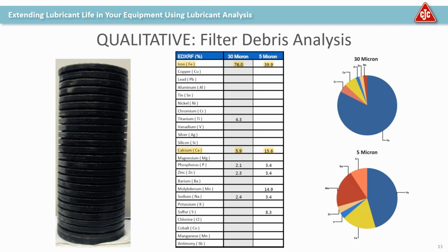And subsequently, this oil has remained in service for many years since this initial cleaning up. The owner was looking at replacing all of the oil, replacing the gearbox even, but instead, just by using routine oil analysis and good filtration, they were able to keep that oil in service, which really is a huge benefit, because for the average wind turbine, the cost savings of just one oil exchange, a conservative estimate, is $5,000.